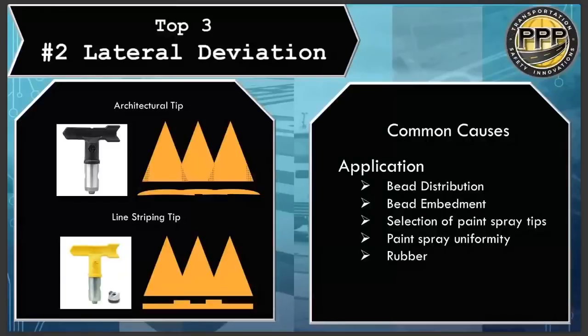Yeah, Justin, I'll just add real quick. We go over this in the symposium, but there are resources available on our website. There's the Airfield Marking Handbook that actually covers some of the calibration process. Calibrating equipment doesn't matter if it's a small machine or a truck. But Greg mentioned the mil thickness. We also do a bead calibration test. So if you have multiple guns, you calibrate multiple.